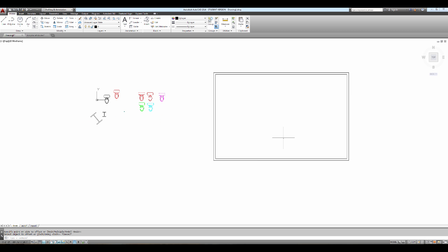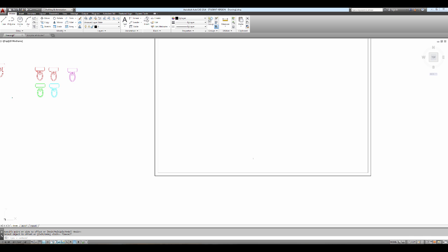So say in here I want to put in a door outside here. I'll go ahead and just draw that in for the door, and we'll offset for 3 feet, okay, for an exterior door, and then I'll trim that out. All right, so there's my exterior door hole. I'll do an interior door right here.